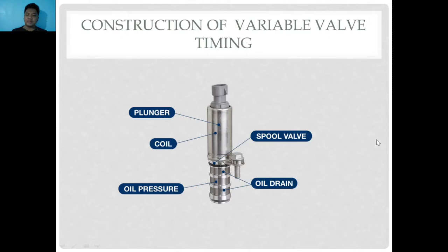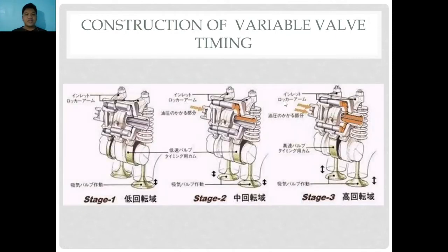It's electronically controlled. And this one is what we all know as VTEC. Unlike the first one, which is just controlling the advance and retardation of the intake, VTEC actually controls more than just that.